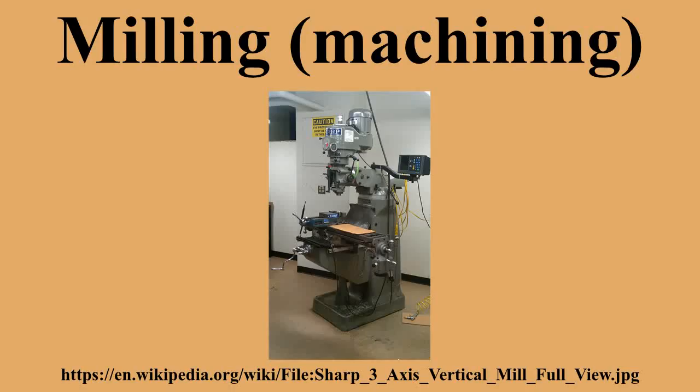The integration of milling into turning environments and of turning into milling environments began with live tooling for lathes, and the occasional use of mills for turning operations led to a new class of machine tools, multitasking machines, which are purpose-built to provide for a default machining strategy of using any combination of milling and turning within the same work envelope.